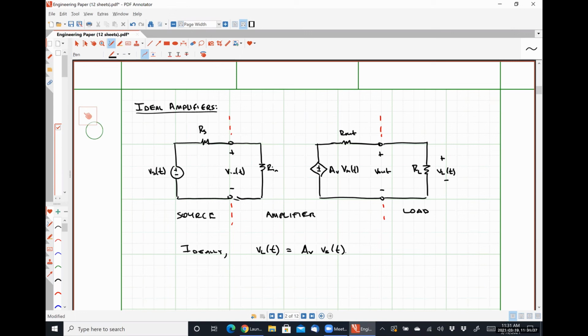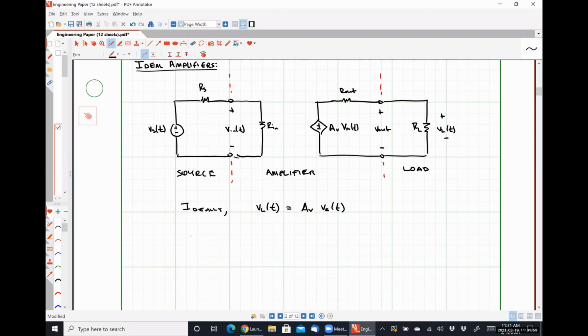So we actually need something on the completely other side of the spectrum, right? If we were to apply an open circuit here, or an infinite resistance, Vs of t would have to be equal to Vn of t because there would be no voltage drop over that resistor Rs. So ideally, Rn is infinitely large.